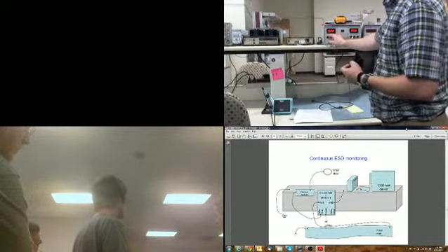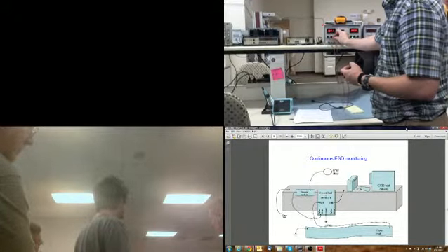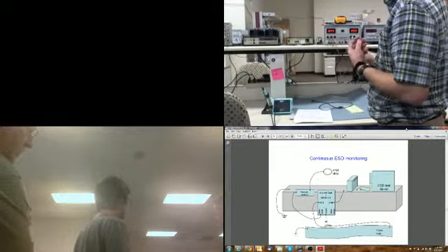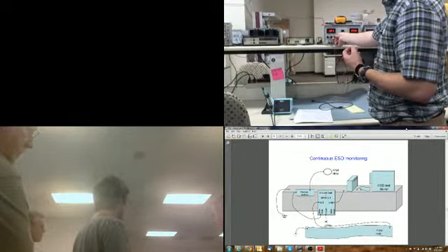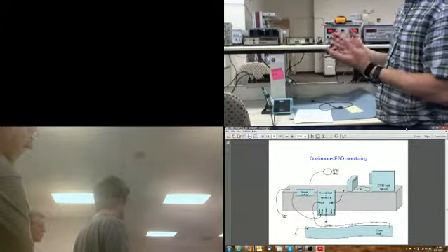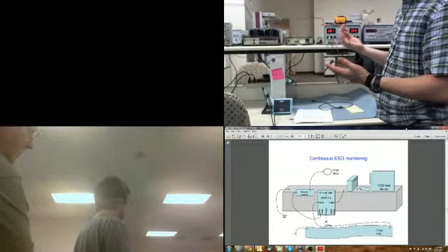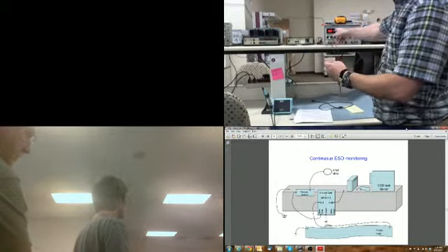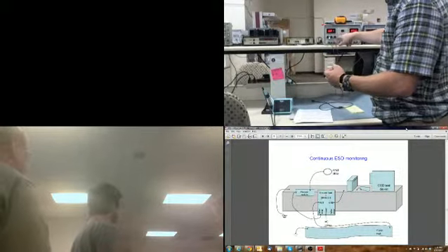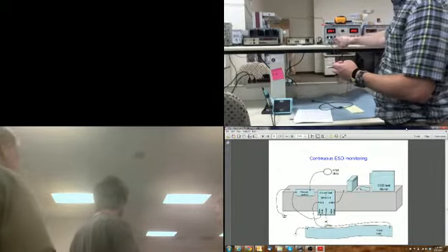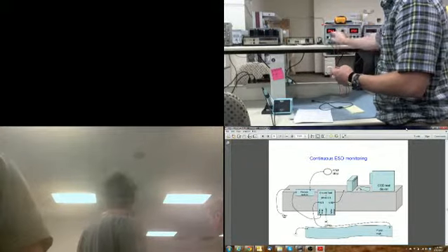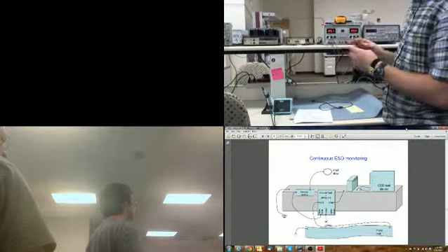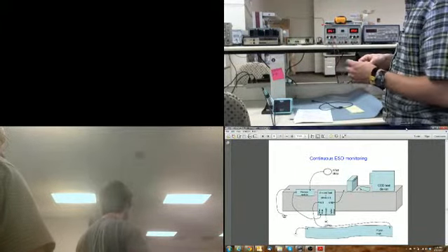Now, as I start to turn up, now it's current limit. As I turn up the current, it's going to increase the current. So if I want to current limit this supply to 1 amp, that's how I would set it. Now when I let go of it, the current goes down to 0. If I put a resistor in here, a variable resistor, then as I change that variable resistor, the current would go up and down. But the voltage should stay the same as long as that red light's not on. If that red light turns on, the way it's going to limit the current is it reduces the voltage. So when you connect, that voltage should drop.